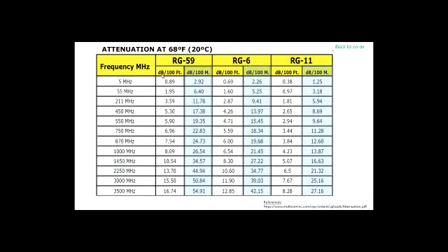Now, dB stands for decibels. It's a logarithmic type of scale. All I'm going to tell you is that decibels is a reference type of unit. That's all you need to know for this presentation. If you have a signal of certain strength and you raise that signal 3 decibels, you're doubling the power of that signal.